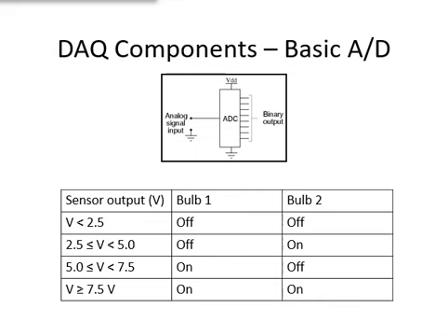The digital representation of the value of the transducer output is a code that is related to the analog transducer output but does not describe the output exactly. For example, we could connect the output of the transducer to a relay, which in turn operates a light bulb. If the voltage is less than or equal to 5 volt, the bulb is off. If the transducer output voltage is greater than 5 volt, the bulb is on. The on-off status of the light bulb is a digital code that crudely represents the transducer output.